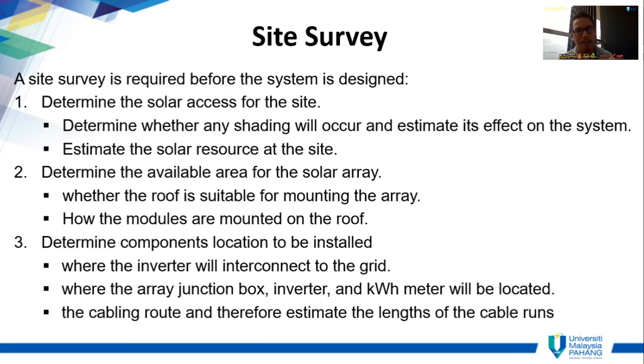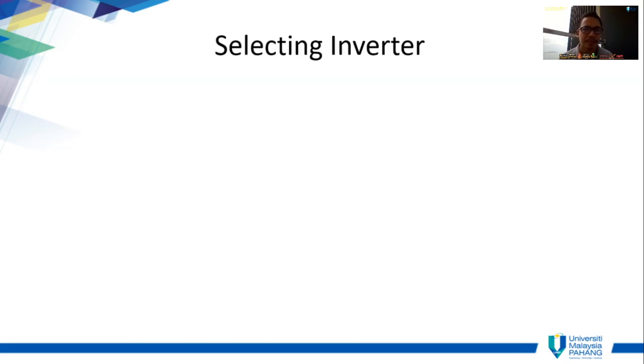7 meters, 10 meters, depends on the cable route. Then cable routing is very critical. Okay, you need to use solar cable instead of DC cable, because solar cable is heat resistant and double insulated and so on. Okay.